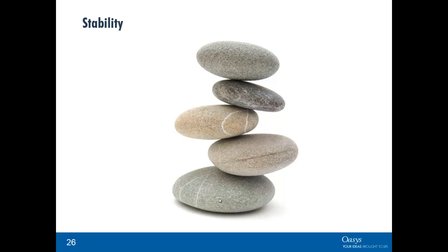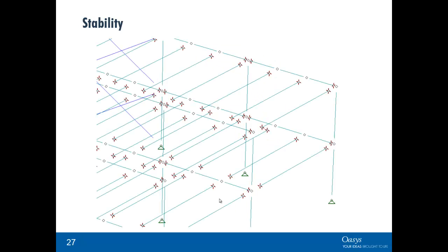Stability in the model. Models have to be stable. Now let's look at this steel frame model here. The beams have got pin ends. The column has got a pin support base. The problem is the columns themselves are torsionally unstable. There's nothing to stop those columns spinning about the axis. The fix for that: add in a ZZ restraint on the column base, which, let's face it, you've got 2 or 4 bolts down there on the column base. It's going to give torsional restraint.